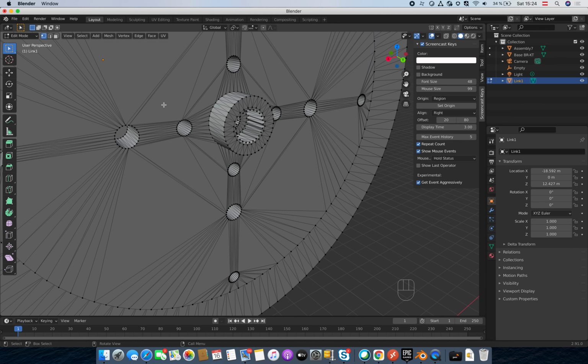So for that, the circle selection is useful. You need to click C for the circle selection, and you can make these circles big. Basically, you can increase or decrease the radius of the circle. So I'm just decreasing it to that side, and then you can click and move, and while you are moving you are selecting these vertices.